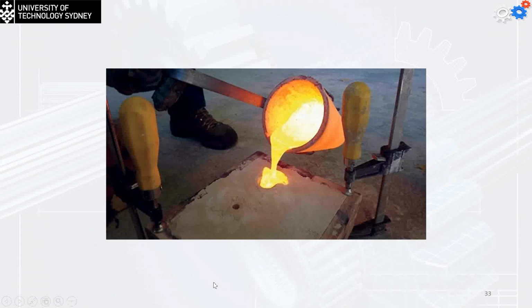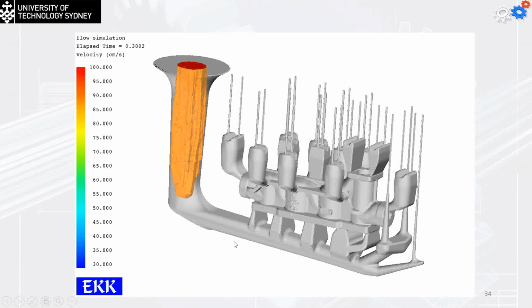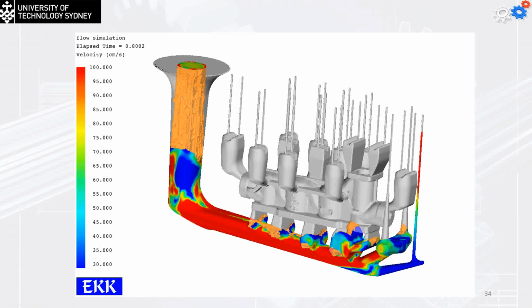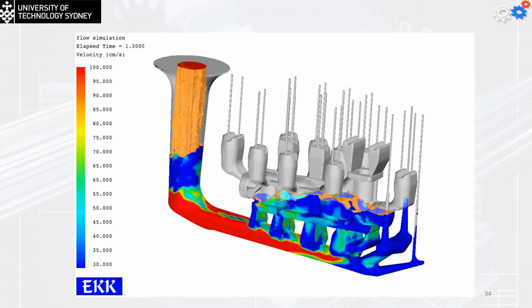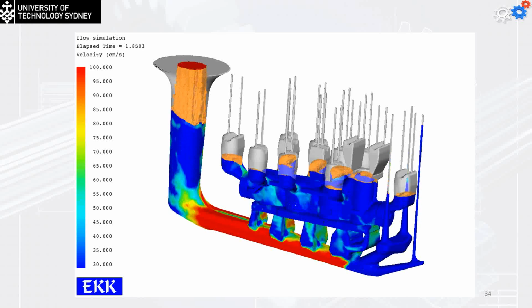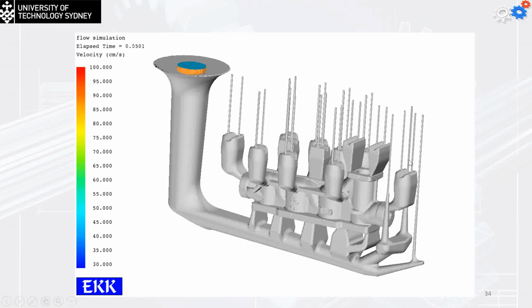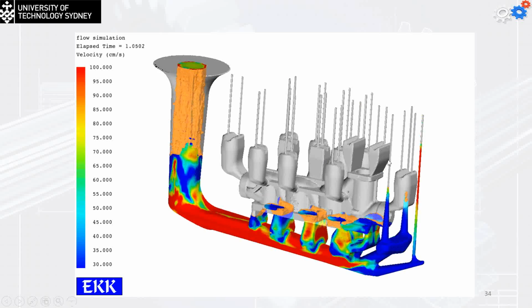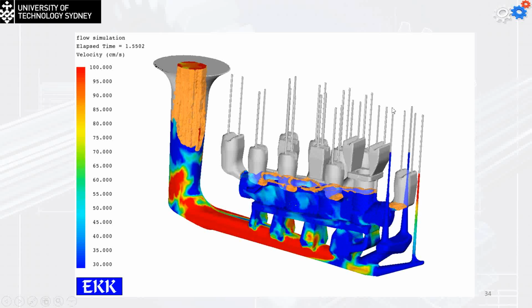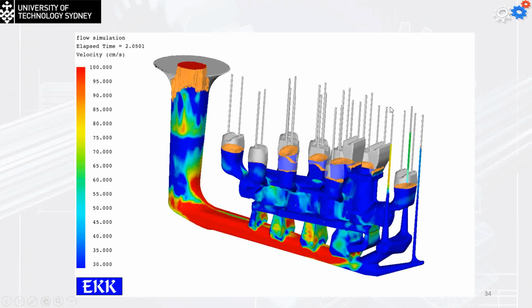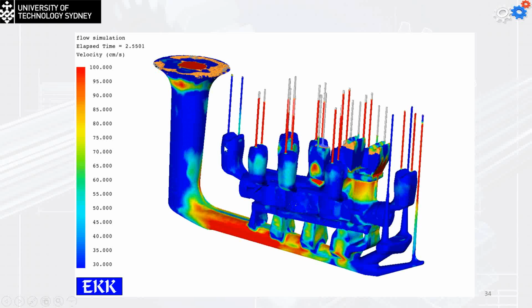Okay, so that's how the pouring of the metal works. We are always going to have an escape for the gases we generate during the pouring process. So that's what will happen. We pour the metal, and it's going to start to fill the cavity, losing temperature at the same time, and the solidification will simply happen. Now these are small tubes. Actually, as we mentioned earlier, they are the risers, and they also provide an escape for the gases and the unwanted, excessive material.